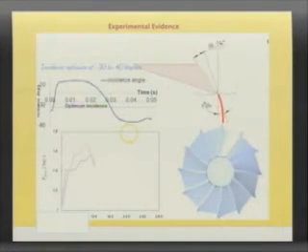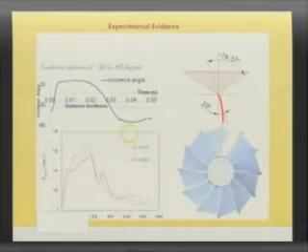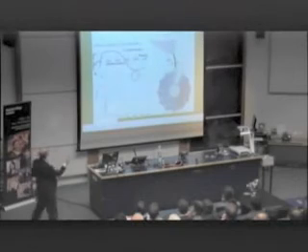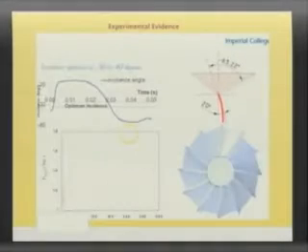And there will be a question at the end of the lecture as to anybody who can tell me why it's a good angle. I'm sure some people will tell me why it's a good angle. So that's a bad angle. That is a good angle, minus 30 degrees, minus 40 degrees. Optimum incidence. That means that the flow is aligned to an optimum direction that enables you to have good energy conversion. And yet we've just seen that that triangle is all over the place.